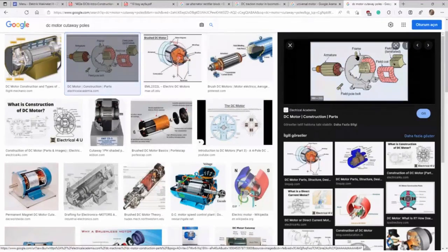The only material that changes is in the stator, because in AC there are iron losses, core losses, because the alternating current induces Foucault or eddy currents. They cause eddy current losses and hysteresis losses. So to keep those kinds of losses down, we generally use silicon steel sheet material in AC machines.